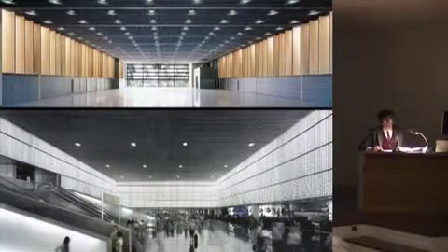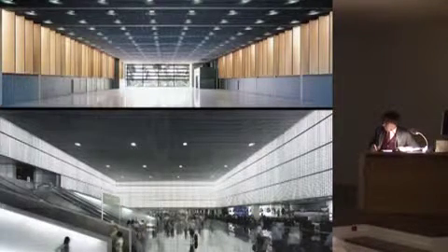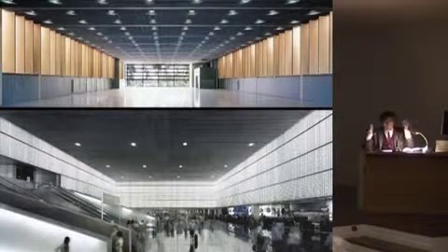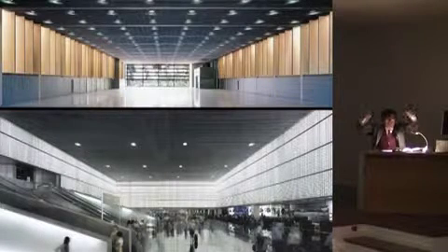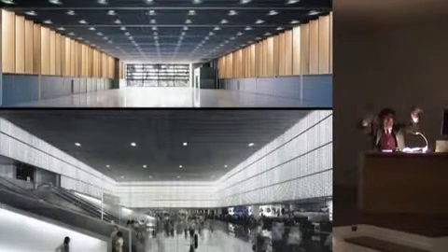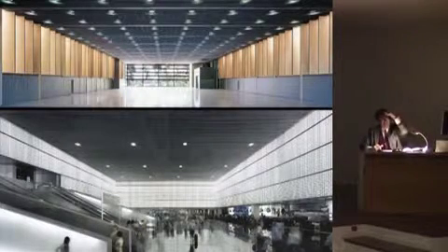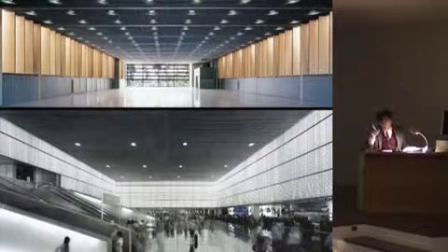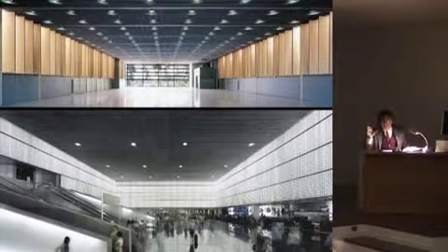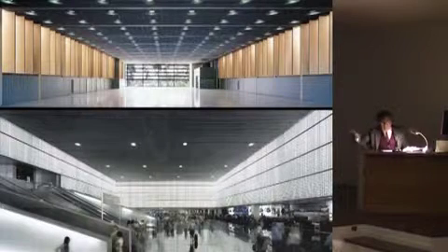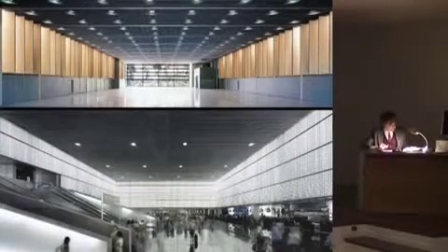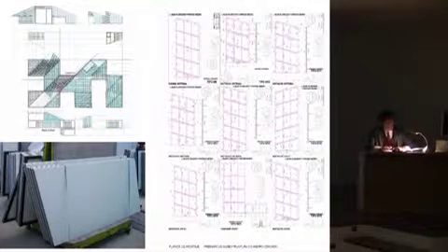And with Ramon Sanabria, we worked on this ceiling for the intermodal terminal in the Barcelona airport when Spanair was there. So you hide everything and you can record and log everything because you just let the hooks go and clack, the cover opens and you can work on any fitting inside because then you can see everything. So, an advice: do not embed, do not hide the fittings. You want to see them always, because if a pipe breaks, you need to find it and you have to dismantle the whole building and you don't want to do that.